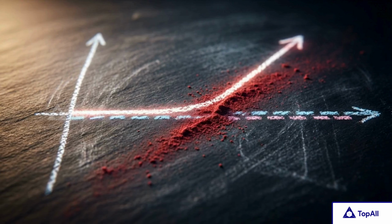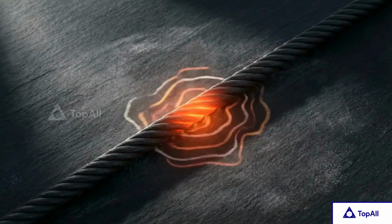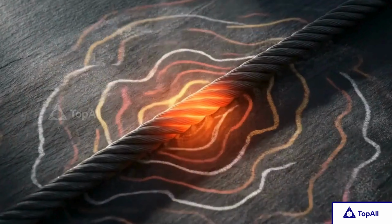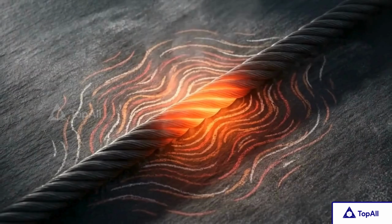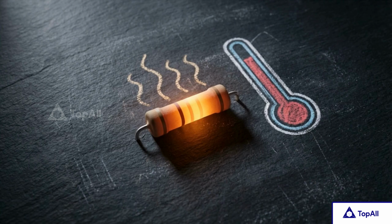In this curved region, the voltage no longer generates a proportional increase in current. Thermal energy causes this deviation. High currents increase atomic collisions, which generates heat and subsequently increases the resistivity of the metal. We calculate this change using the temperature coefficient of resistivity. This coefficient measures the precise fractional increase in resistivity for every degree of temperature rise.